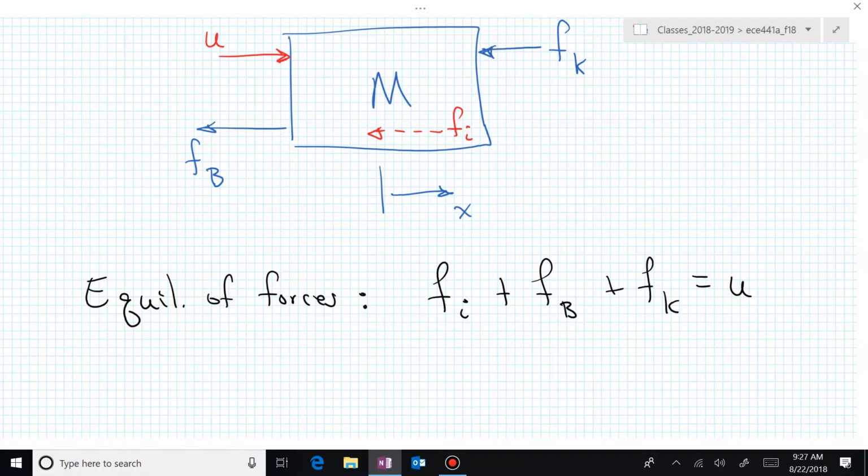Did that answer your question on the inertial force? It takes a little getting used to, but once you use it, I think it makes it easier to write the equations. You don't have to keep asking which direction is x, or remembering to set those forces equal to mass times acceleration. Now it all just works out, if you remember that this inertial force, F sub I, is capital M x double prime, or capital MA, mass times acceleration.